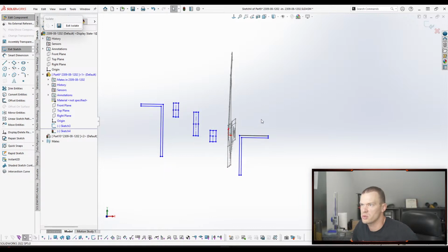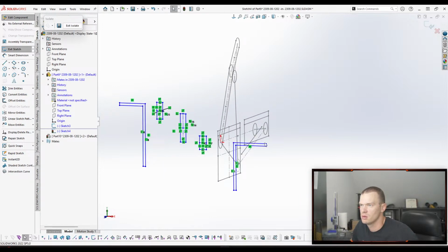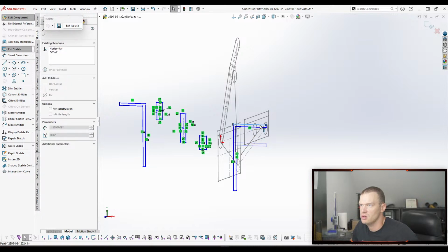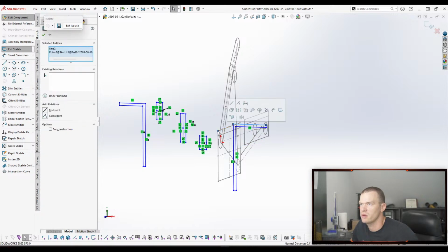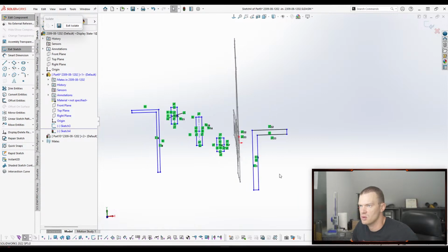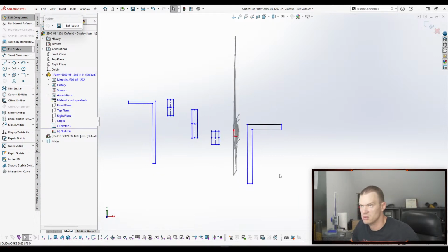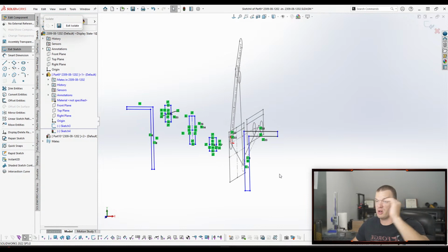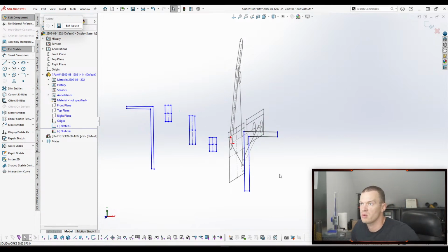And we'll control this with the geometry that we already have. So this doesn't go here. This is going to be in line with this. And this will be in line here. And again, we're using that sketch geometry that we already have to control these dimensions. We don't want to put another dimension on here when we already have a sketch that has geometry that we can reference.